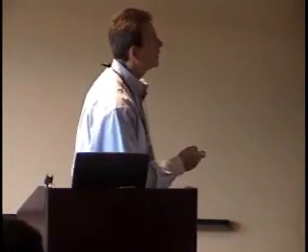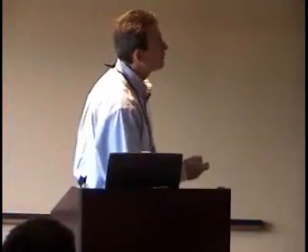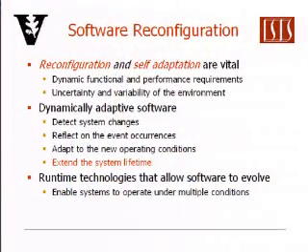Both the localization and the synchronization algorithms have been driven by the shooter localization application, where the objective is to localize a shooter in an urban environment using acoustic sensors. This is achieved by sensing both the muzzle blast and the shock wave of the shot, and using the localization and the time synchronization algorithms, the 3D accuracy of this algorithm, as demonstrated at a marine base, was around 1 meter, and the latency was less than 2 seconds. So these are some of the things that are going on at ISIS, but today I'm going to talk about